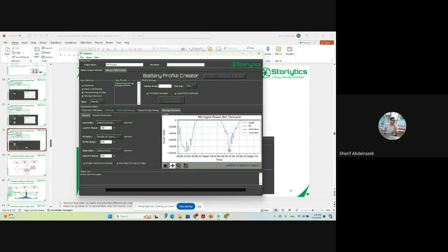Let's assume this is 9. Because this is 15-minute resolution, this is 8 to 12, so that's 4 hours and you have 16 data points between here and here. So it's basically taking, let's just talk hourly, over the hour the average power, and then since it's an hour, you can consider that energy.